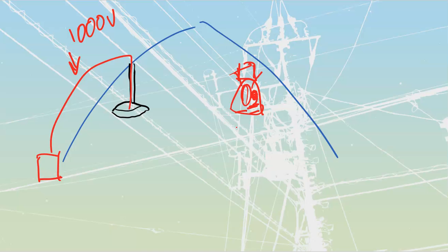The last one that they talk about is going to be a high-low ballast. Very uncommon. I would not expect to see these, but they do have some of these that have been manufactured in the past. We probably won't see a lot more manufactured in the future with LED, because with LED we are actually able to do a lot of dimming. But the high-low ballasts are going to give you the ability to have like two separate values of voltage and current that you can run off of them.